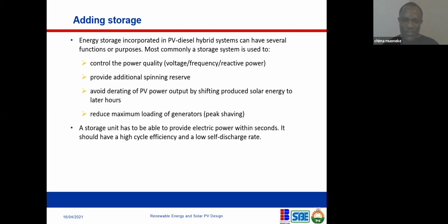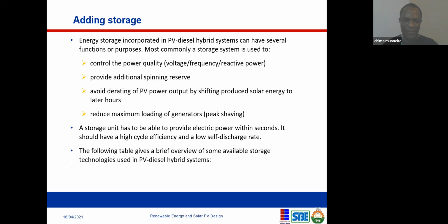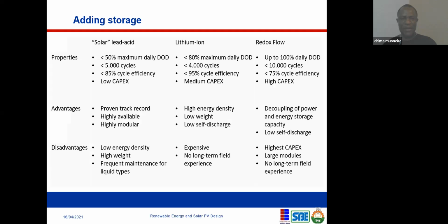So a storage unit has to be able to provide electric power within seconds. It should have a high cycle efficiency and a low discharge rate. The following table shows a brief overview of some available storage technology used in PV diesel hybrid systems.